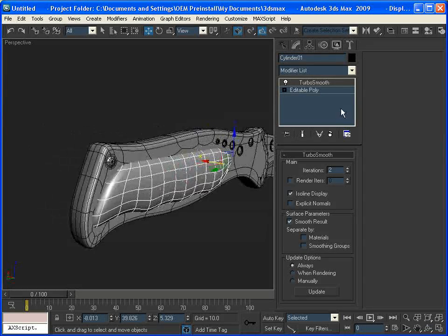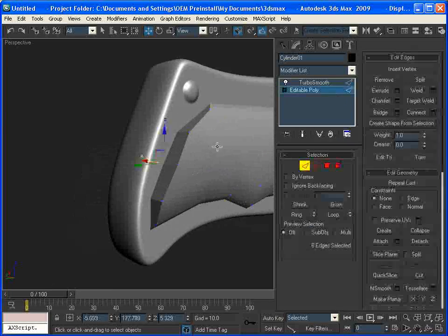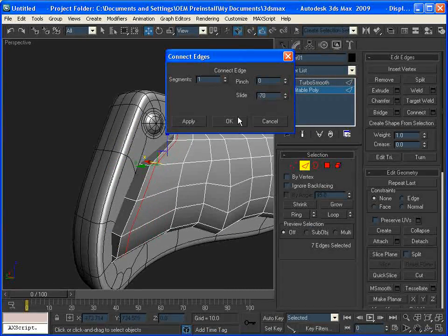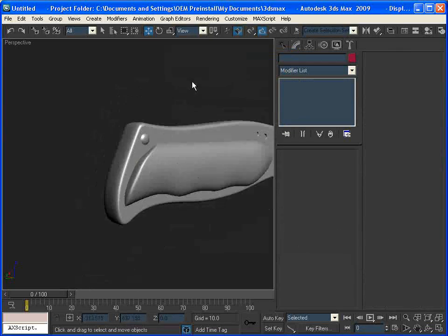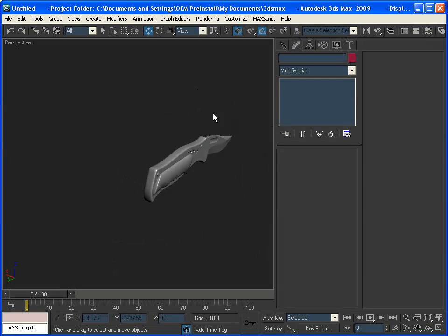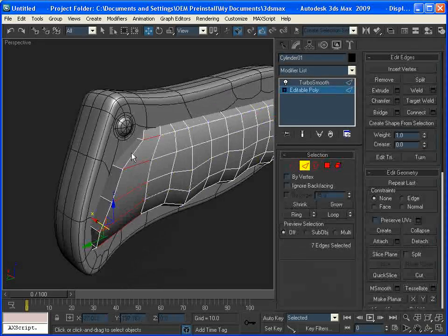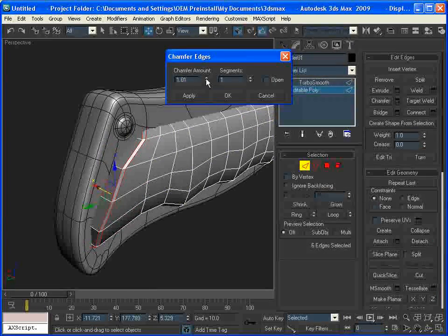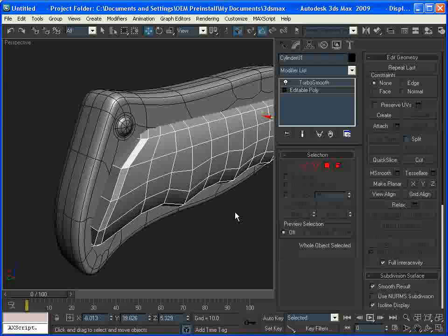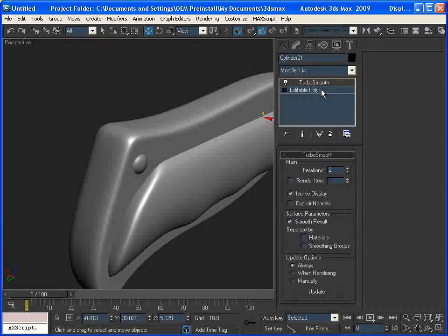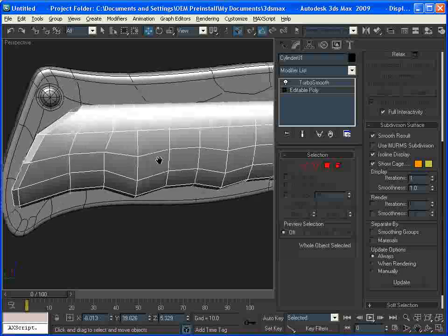Could maybe use to be a bit more tight in the back, so we'll throw a supporting edge on there. Alright, we could also just chamfer that if we wanted, which would mean just selecting this loop, chamfering. It'll probably give fairly equitable results, but the thing is, if we wanted to change that later, there'd be no easy way to.